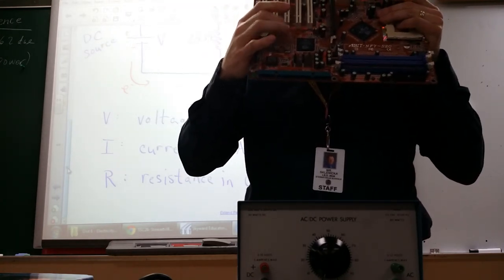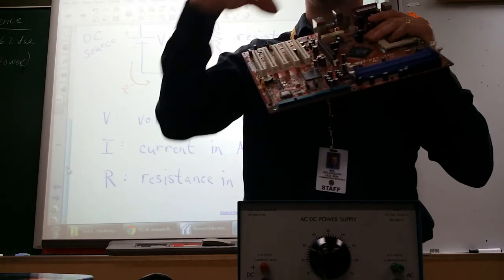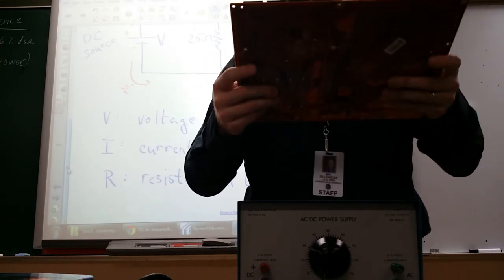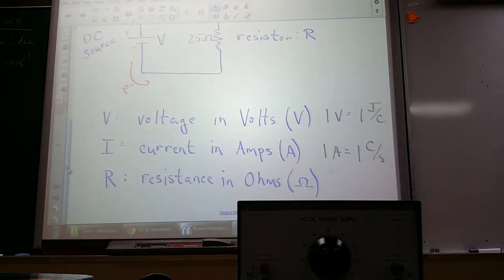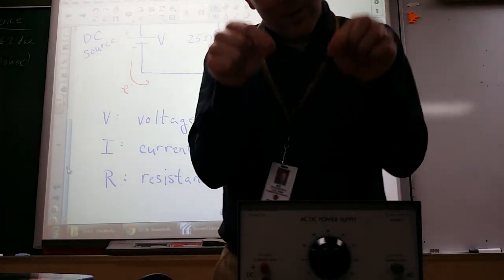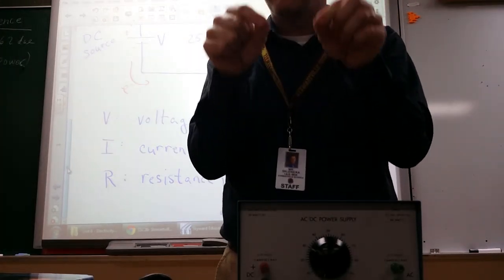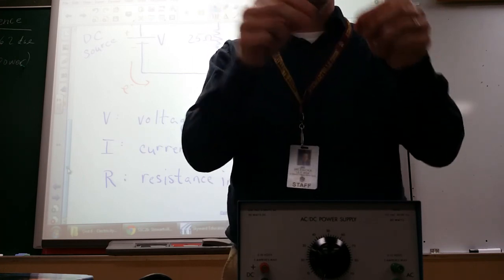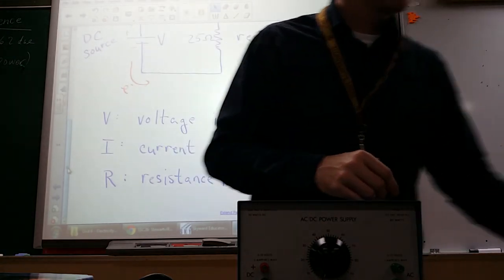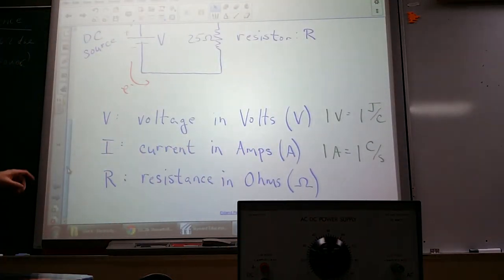And they're very useful for populating on boards like this because they're all done by machine or an unlucky electrical engineer who has to remove a whole bunch and replace a whole bunch of them just to test out what his board is going to be doing. You end up using 2 soldering irons, pinching them in between the soldering irons to heat both sides at once and looking at it through microscopes to be able to place your components. It's not actually as hard as I'm making it sound. It's okay. Okay, so that's our resistance.